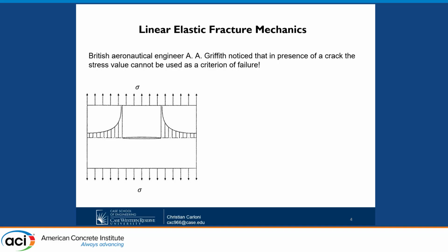You have the same stress concentration in holes when you do your gusset plates for trusses, okay? But when you have not a circular hole, but a crack, this stress concentration is really high. So when I teach my students this part, I say, well, if you learn strength of materials, there is something that doesn't fit the whole statement, because that would mean that near the tip, even if you apply a very small tension, you will have the crack propagate. So what we learn in strength of materials as engineers does not apply whenever there is a crack. And I'm not saying you have to see a large crack. You can see a defect, something that is embedded in your material, okay?